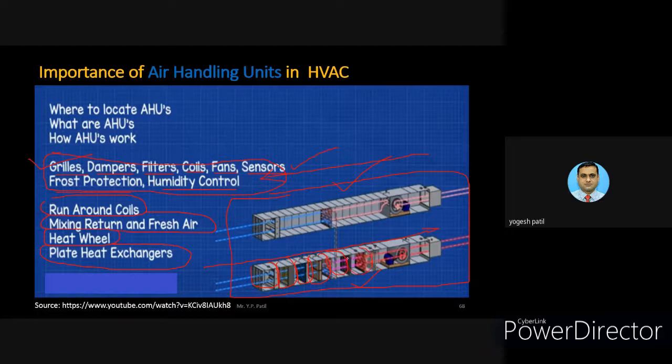You can see there are different zones in a particular air handling unit, and in the exhaust the zones are fewer, only two to three zones on the exhaust side or return side. This is the supply side. Supply side means that the external ambient air gets supplied, and the return side is where the air from the building gets exhausted to the atmosphere, sometimes directly, and sometimes some amount of that air can be recirculated.